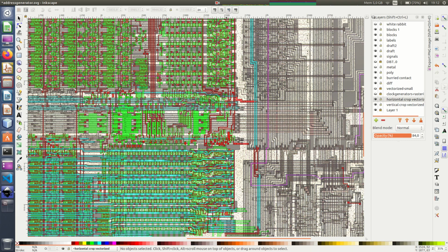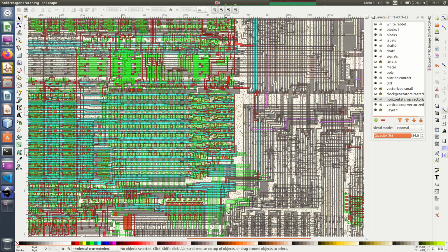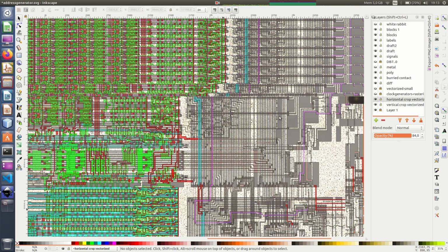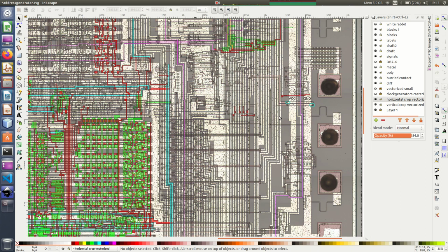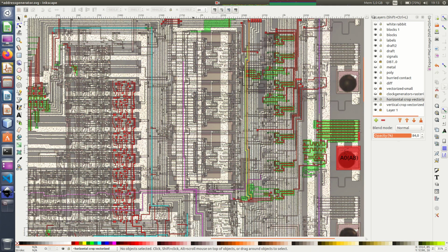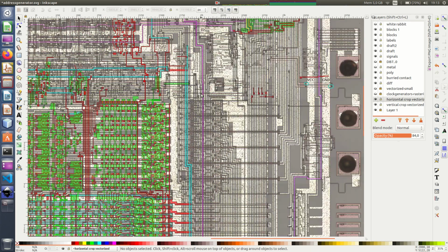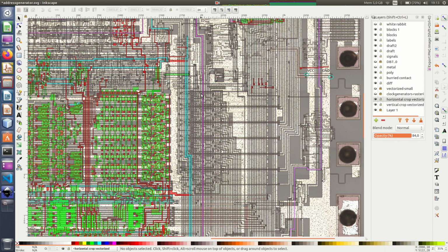Another funny thing about this counter down here, you have 8 megahertz down to 1 megahertz on this bit, but there's no clock division. Oh, sorry. There's no counter here. These are synchronous counters, but why don't you have it on the two lower bits? Well, what I do is that I just divide the signal up in the clock circuit. Up here, there are dividers in here. There's really large clock drivers, which are 8 megahertz, 4 megahertz, 2 megahertz, and 1 megahertz.